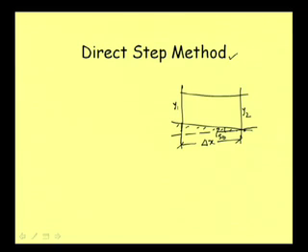Then there will be velocity head, say v1 square by twice g, and that will lead to total head somewhere here, and here say v2 square by twice g, which leads to total head here. I am not considering alpha, the velocity coefficient, here. This line is called the energy gradient line, and the slope of this line is nothing but SF.